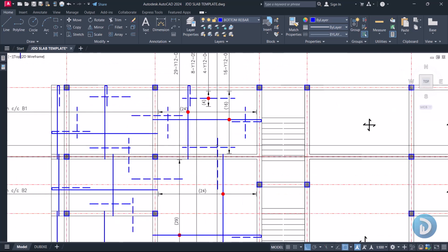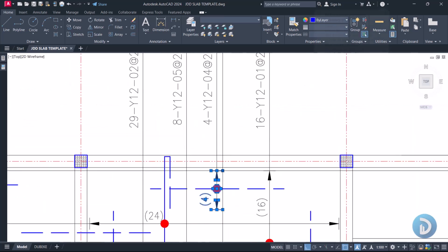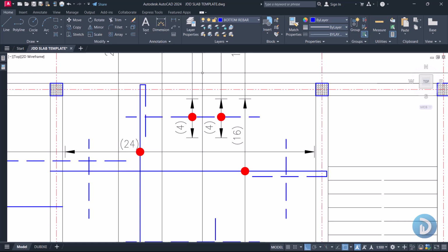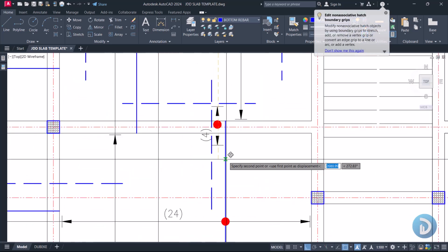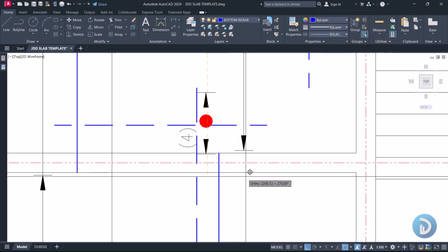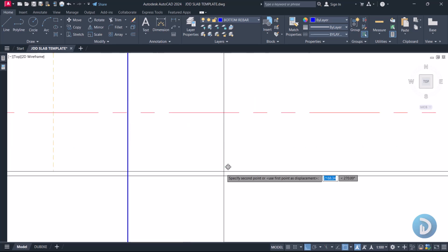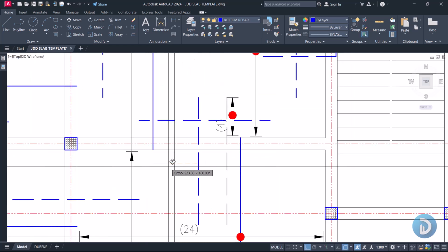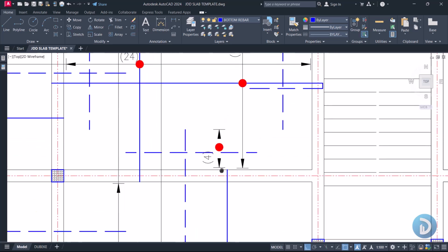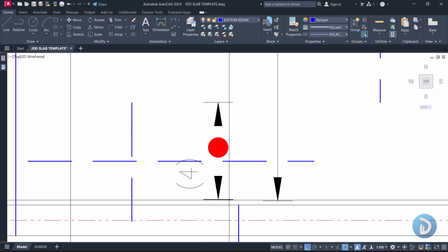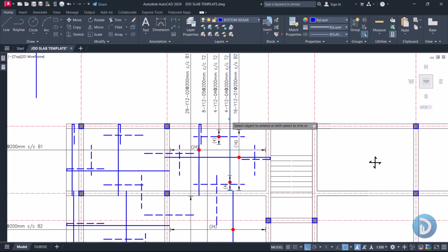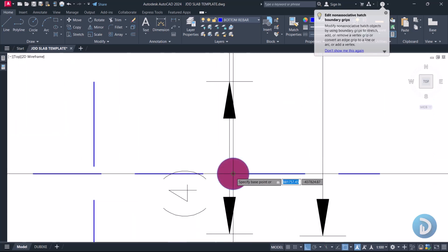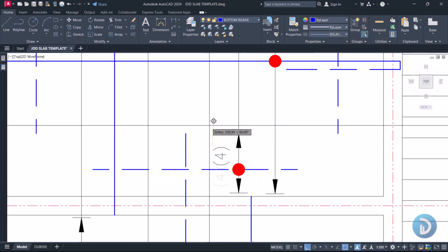Then for this one in the middle of this part, we can as well copy this. Let's copy this here. Okay, then we can move all of this to somewhere here, and let's move out this other reinforcement to somewhere along this path, so we'll have a clearer spacing. Okay, then we can extend our call out line from here to here, and this will be anchoring this very reinforcement. And this is our total length.